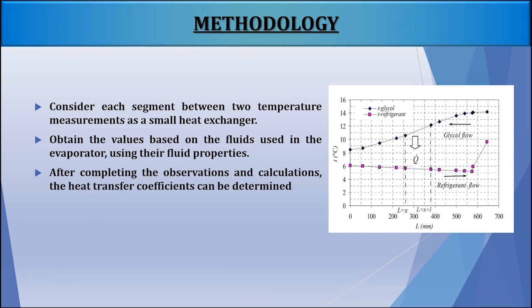In this project, I considered each segment between two temperature measurements as a small heat exchanger. For each segment, I obtained the necessary values based on the properties of the fluids used in the evaporator. Using these fluid properties, I proceeded with the observations and calculations. This approach allows for the accurate determination of the local heat transfer coefficients for each segment.